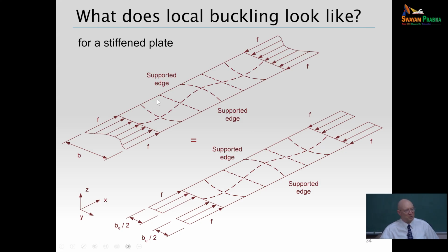Well, if it's got initial imperfections, then it's going to start bending out of plane as soon as we put load on it. But then at a particular load level, those out-of-plane deflections start becoming significant. We get these waves that are forming in the plate. And so we have a situation where the supported edges, the edges kept straight by the supports, tend to be stiffer. We're developing higher stress at the supported edge.